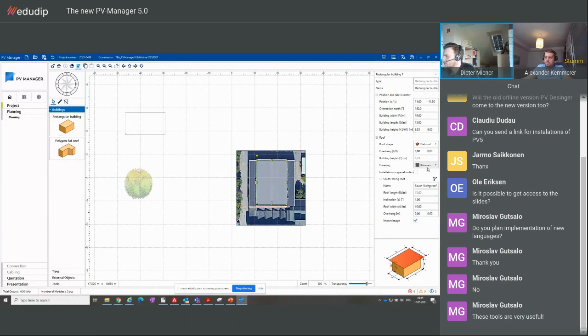Then, which is important to know, is the roof covering, either bitumen or foil roof, to know which secure mats under our base rails, for example, are needed for our Aerofix system, or which static friction coefficient is used as standard. And you can also install on gravel surface if you want.